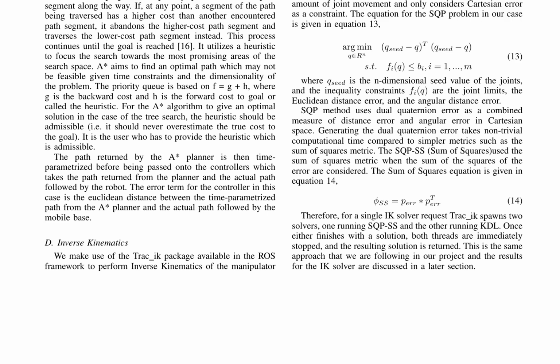The research paper discusses the implementation of a pick-and-place task using the Fetch robot, which involves both trajectory planning for the manipulator and mobile base, as well as controlling the gripper action. To achieve this, the authors utilized a state machine in C++ that automates the entire process by transitioning between different states upon receiving ROS messages after completing previous tasks.